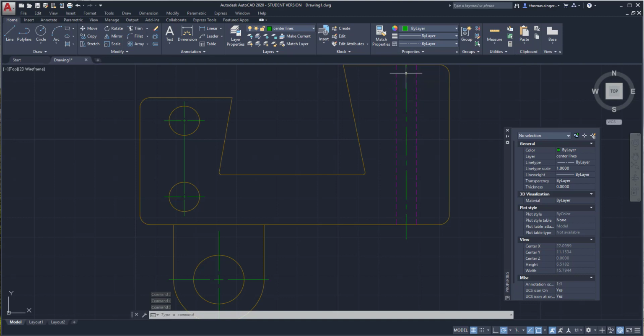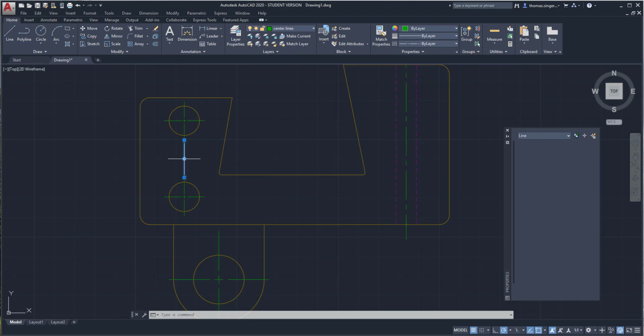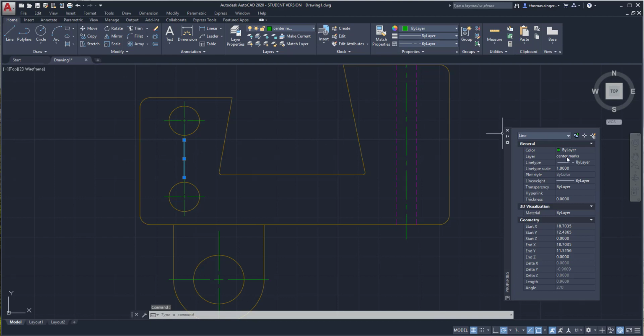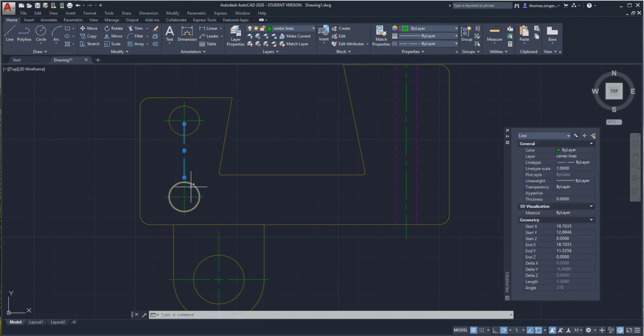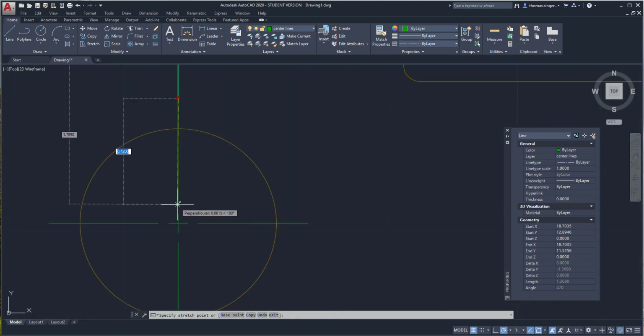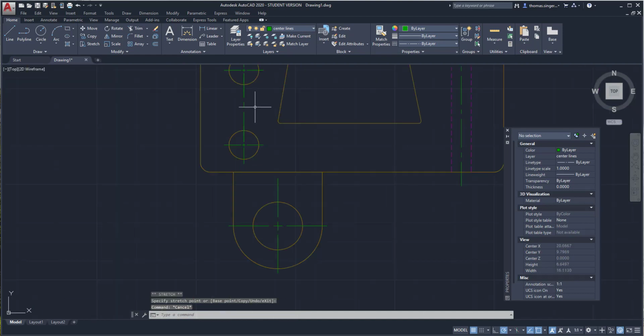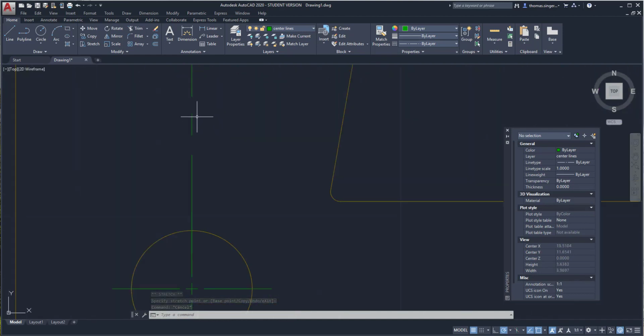Now that added additional breaks here but didn't change anything here because this is still on the layer called center marks. Well, I can change that by putting it onto the center line layer. So still nothing. What if we were to extend this line a little bit farther? Would it help? Now all I did was connect it to the endpoints of the existing line. And you notice that when I do that, I lengthen it long enough that we actually get a break in here.